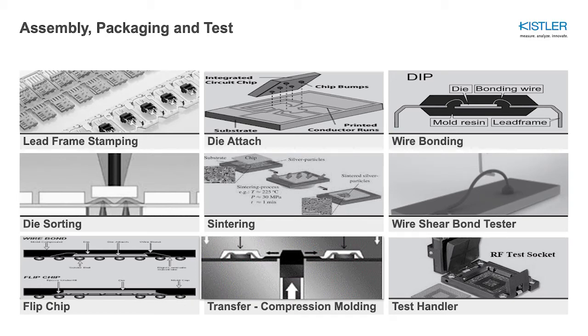Further, piezoelectric force sensors allow measuring a wire bonder's dynamic force in real time. Typical low forces like 0 to 10 Newton are measured in milliseconds and grams and can reveal potentially damaging conditions like head bounce, vibration, and malfunction during operation. In addition, semiconductor equipment manufacturers can use the signal for accurate and precise closed loop control.